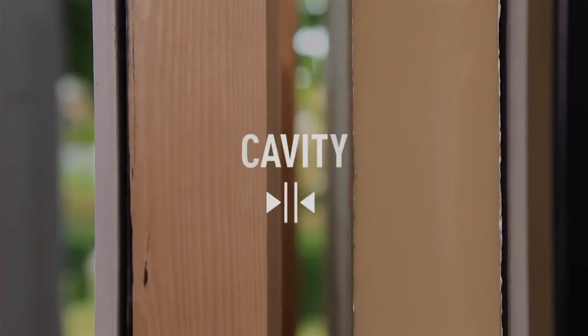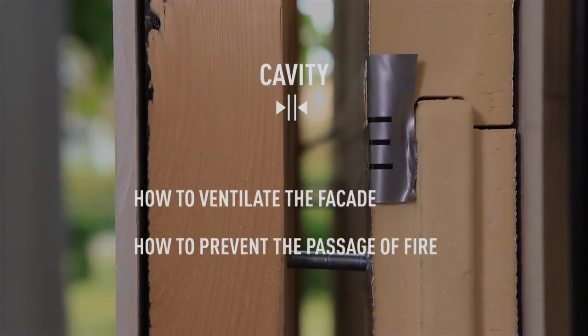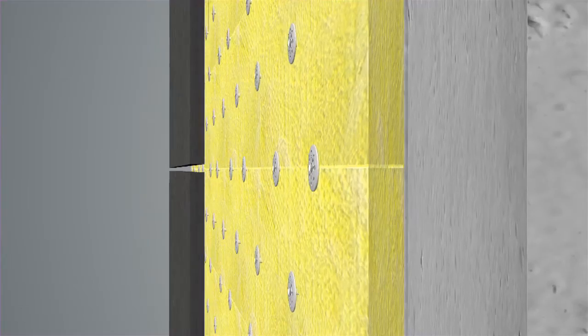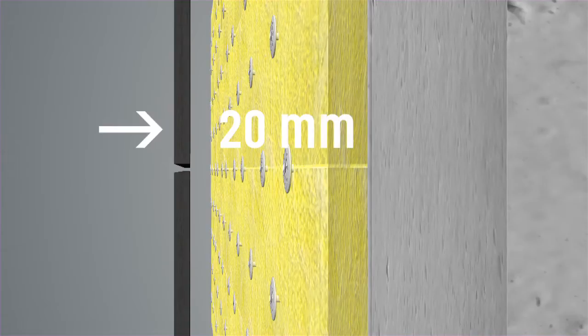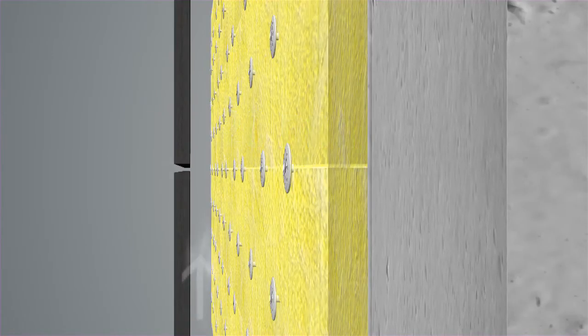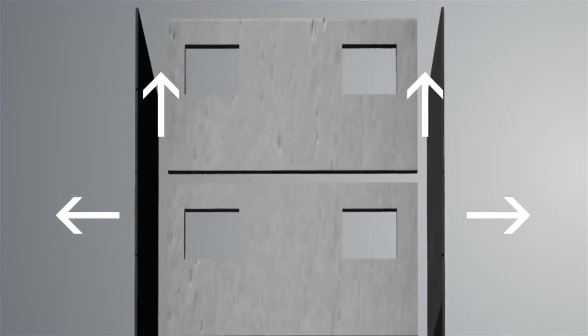Cavity. Now we look at how the facade is ventilated and how to prevent the passage of fire. The minimum cavity width should be 20 mm. This will permit both air movement to evaporate moisture and a drainage path for water to run down the rear of the panels and out at the bottom of the cladding. Please note that this 20 mm is only suitable for low-rise buildings and will increase as the building gets taller.